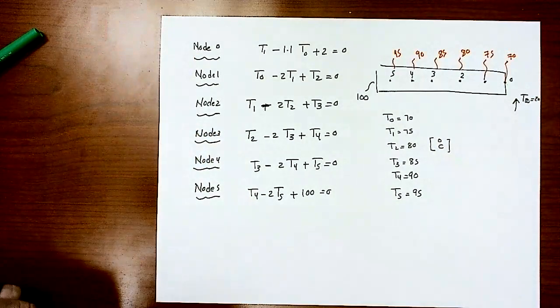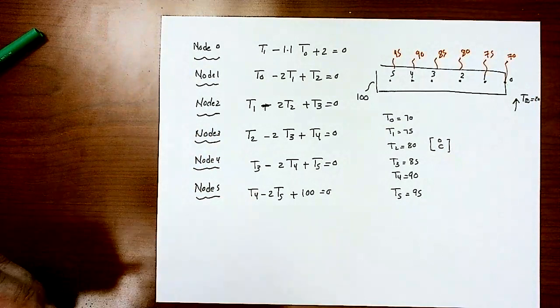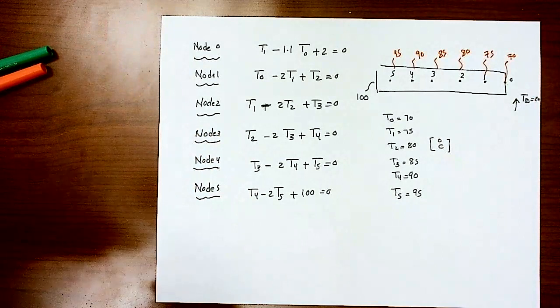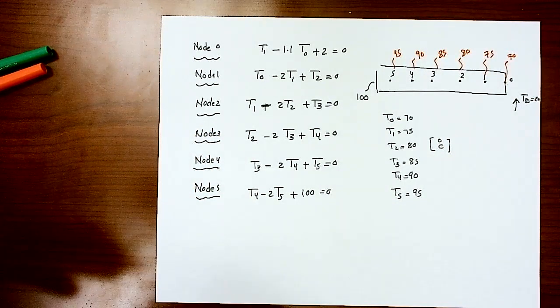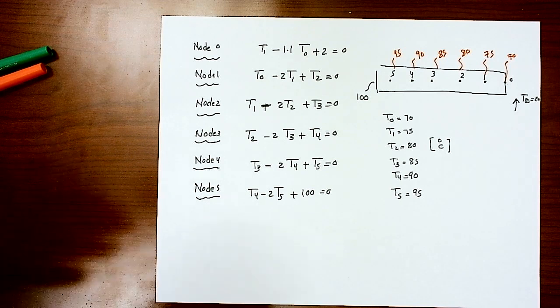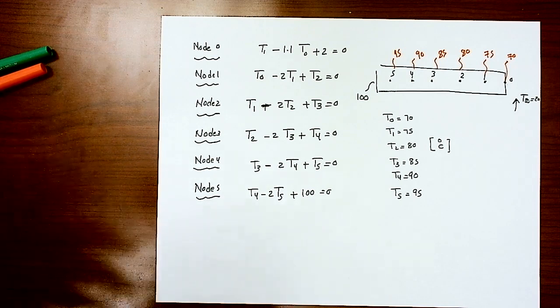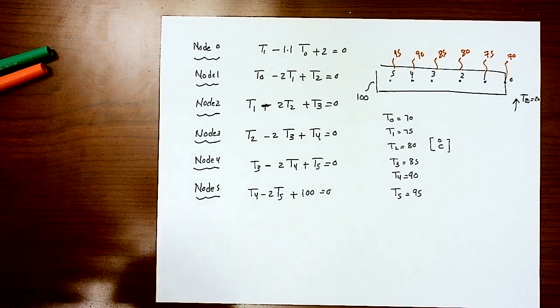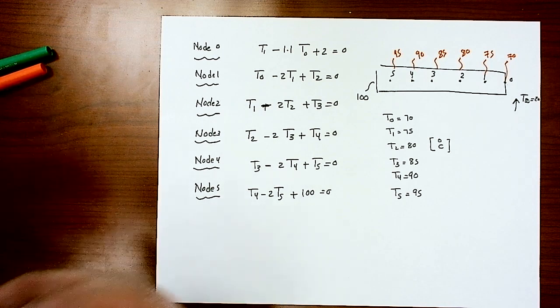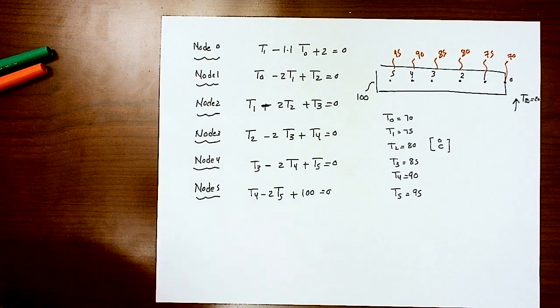And the convection outside. So this is how the energy balance method works. Finite difference method works great, right? But in some situations, we have to use the energy balance method. As soon as you add heat generation into the system, now you have to consider that term, which is going to complicate the issue a little bit. But still, energy balance and finite difference method can be mixed and used all the time to solve that problem. Let me just highlight one thing here.